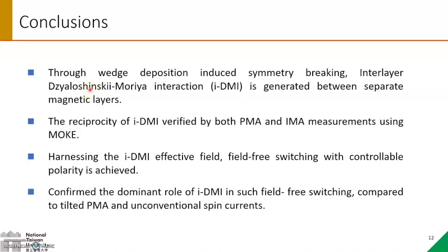The conclusions of this presentation are that through wedge deposition-induced symmetry breaking, the interlayer Dzyaloshinskii-Moriya interaction is generated between separate magnetic layers. The reciprocity of IDMI is verified by both PMA and IMA measurements using MOKE. Harnessing the IDMI effective field, field-free switching with controllable polarity is achieved. And lastly, we confirmed the dominant role of IDMI in such field-free switching compared to tilted PMA and unconventional spin currents.